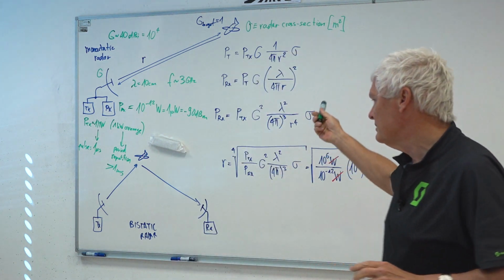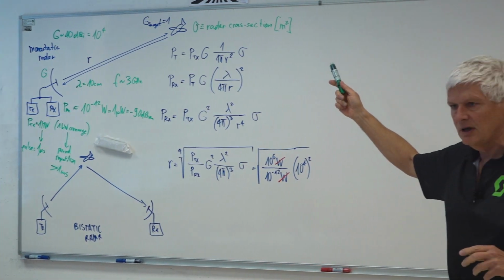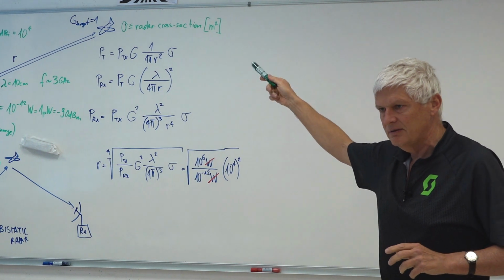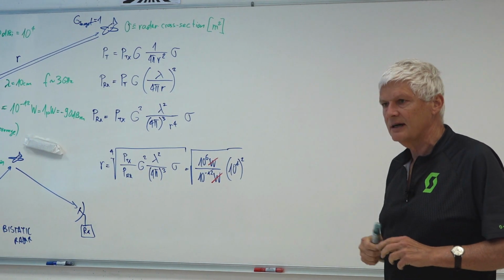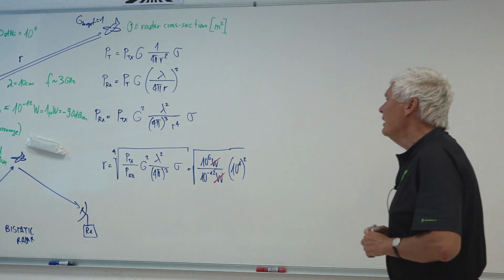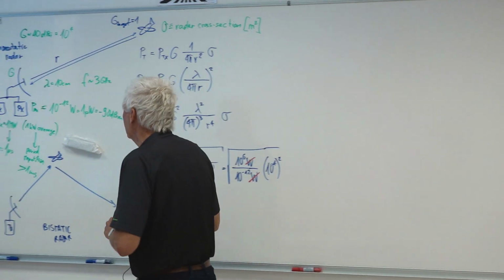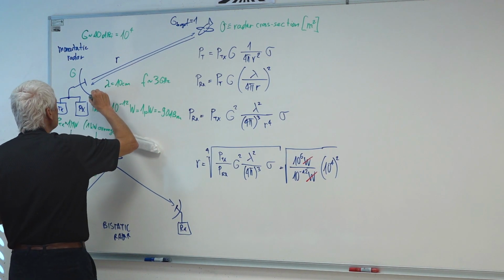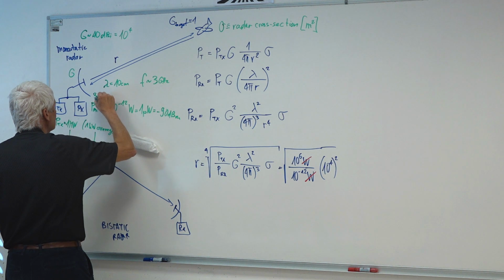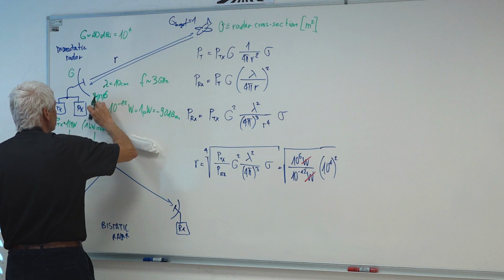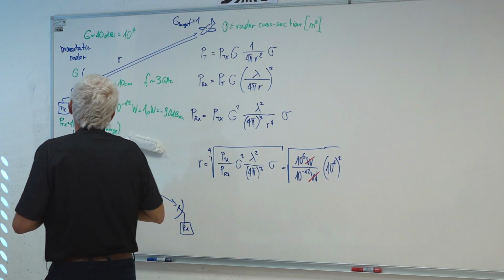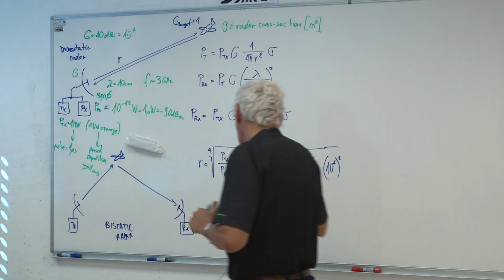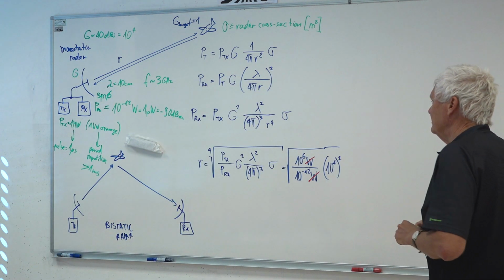Also the radar on Ljubljanski Vrh above Vrhnika, if you ever saw the ball there, is also 3 gigahertz, also a military radar. All of them have about the same, and this corresponds to a dish antenna of about 3 meters diameter for the given gain, just to give you an idea how large the antenna is. 3 meters diameter for a radar installation on a mountaintop is not that bad.